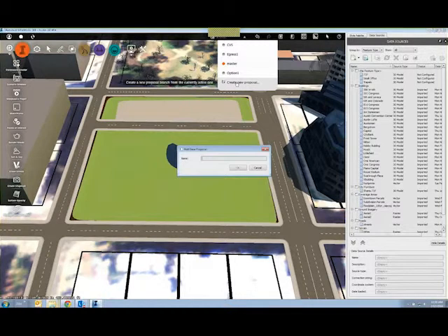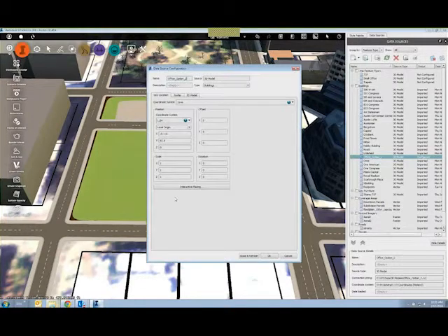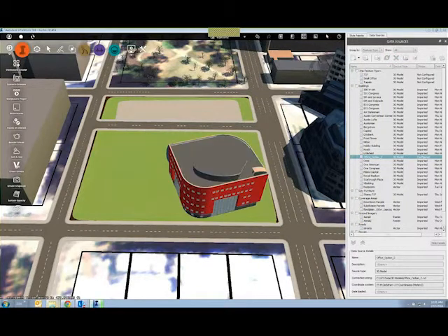They looked at the development costs, they looked at that office option that I threw out there, and nobody was a fan. I've got a different Revit model worked up, a different floor plan, a different layout, and this lets me work with a little bit different setup on the site. All of these pieces can be connected from InfraWorks into the rest of the Autodesk design suites. So we can take this directly from InfraWorks to 3ds Max. We can also take this directly from InfraWorks into Civil 3D. So I can take the site, I can take that road, I can take those outlines and begin processing them in a design application as opposed to this conceptual sketching application.